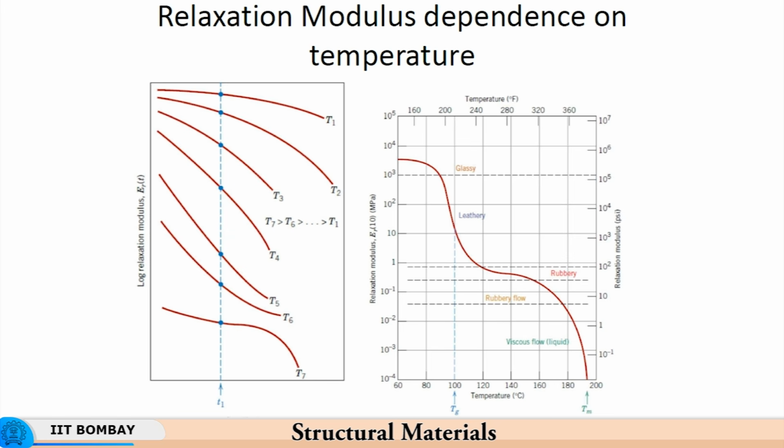If you have held the metal to a certain amount of strain, it will tend to get into the plastic regime, because the shear strength of the material comes down, the material tends to soften, and then there is no time dependent change in the load. So what I am trying to drive at is a time dependent change in the load. That time dependent change in the load is a property of viscous flow, and that gets incorporated into a polymer, and it is not found in metals.